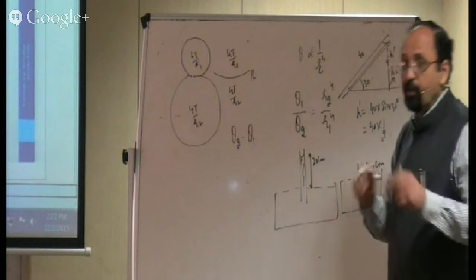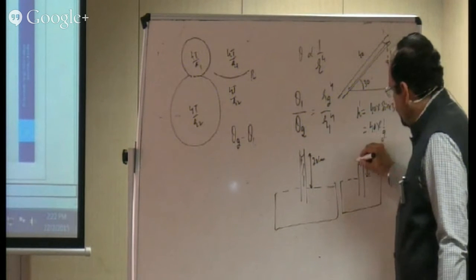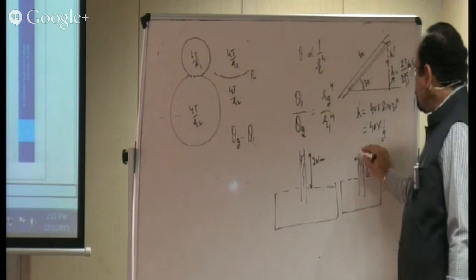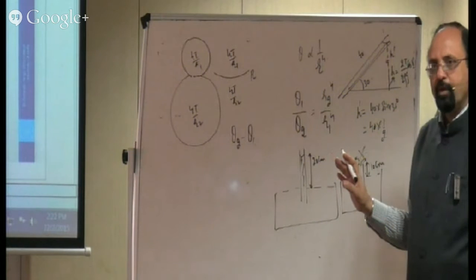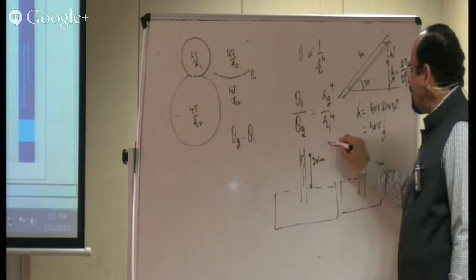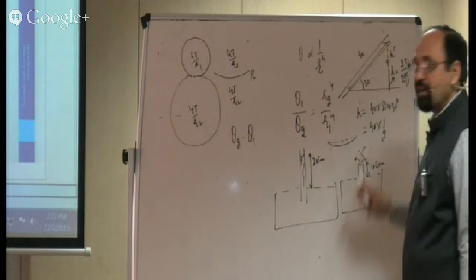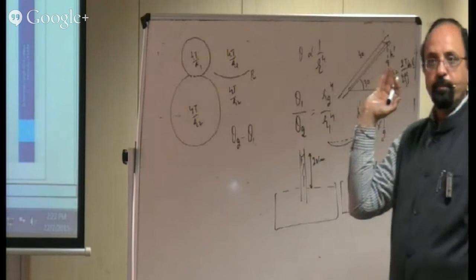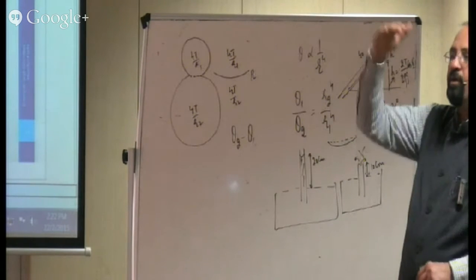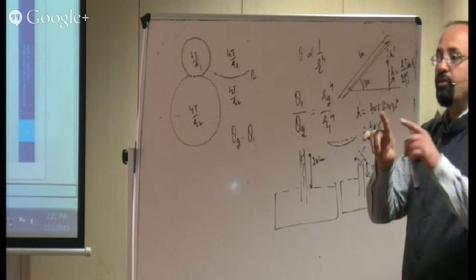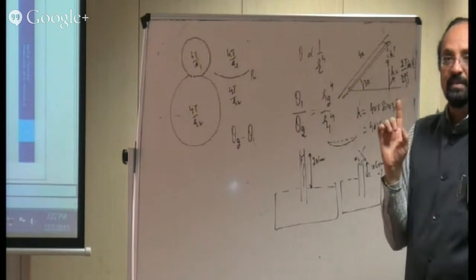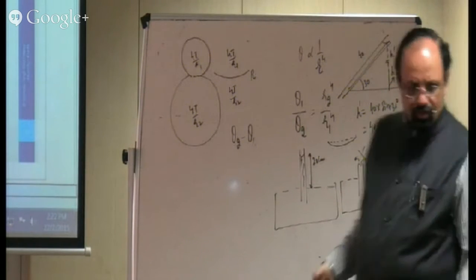But in no case can the liquid ever come out of it on its own. If you do it forcefully, that's a different matter. Only thing is that the meniscus becomes, say, from the more curved to the less curved, and makes the balance at the uppermost position of this capillary. Right? In case of the small size capillary, you must remember it. Whatever the expected length is, if that length is not available, the liquid won't come out of the capillary. It remains up to the top and tries to adjust the meniscus. This is the point, remember, an additional thing.